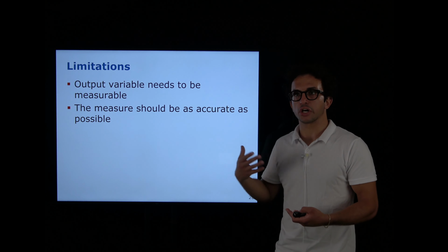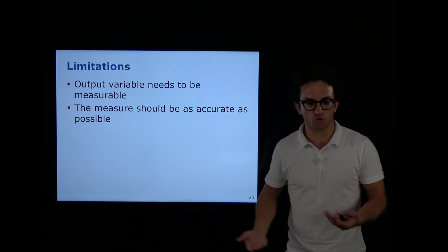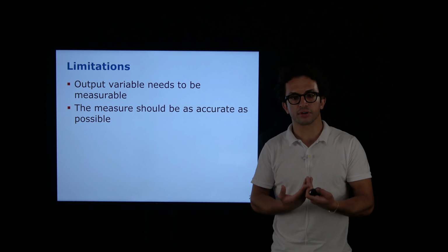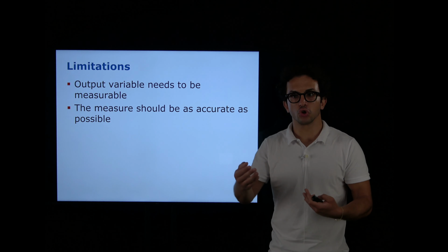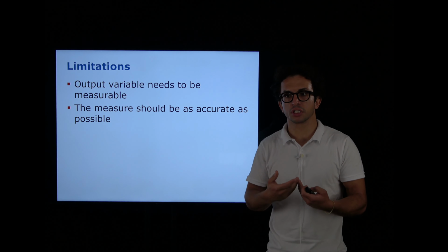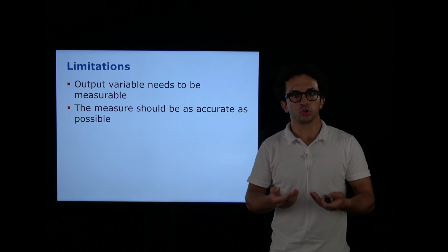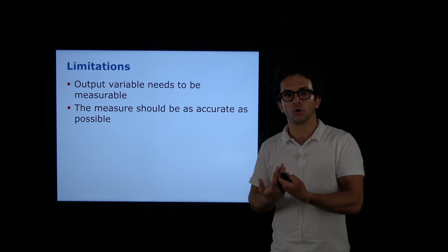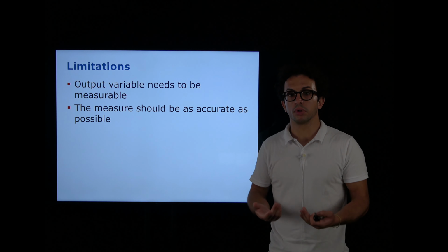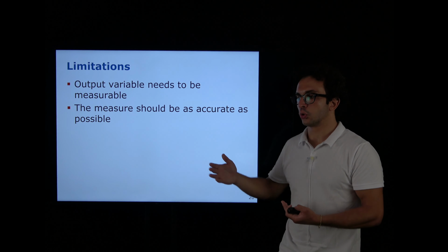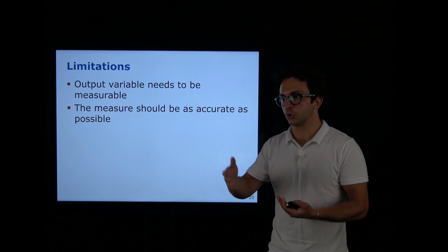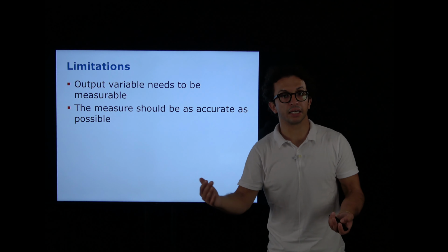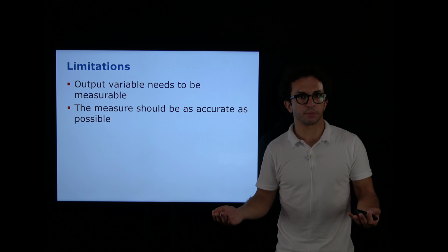If the sensors are not good, they are giving a wrong measure to the controller, which will result in a wrong error, which would result in a controller giving a control action which is not aligned with what you want. It doesn't actually deal with what's going on, which is a big problem, because then the controller is trying to hit a set point which is something else, something that you are not specifying, and that might be dangerous in some cases.